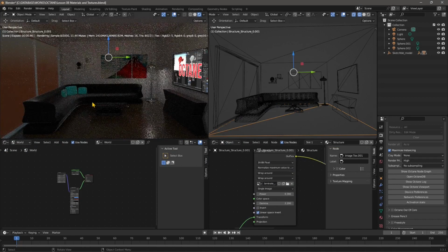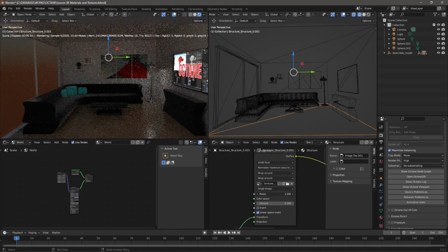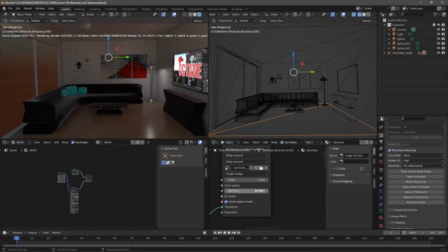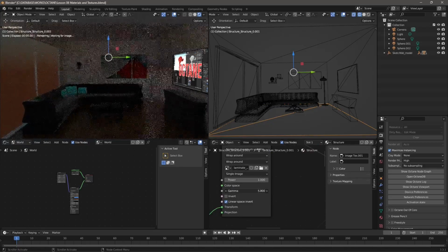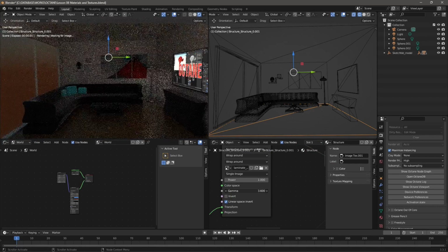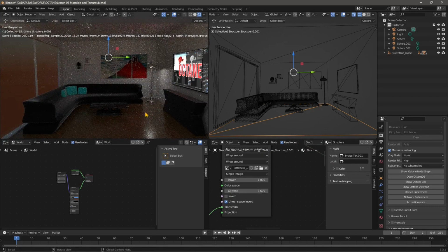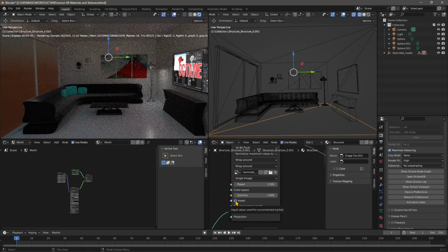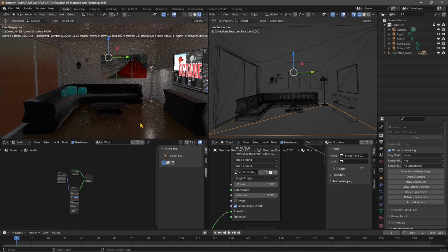So you can see here I'm adjusting the power, and when I decrease the power, it's going to show what's beneath that superficial layer, which is kind of a black surface. But also gamma, you can see you can make things darker or brighter, so you can work on your customization for a texture that you have downloaded and use it. You can also invert, which is going to make the inverse of the texture that you have.